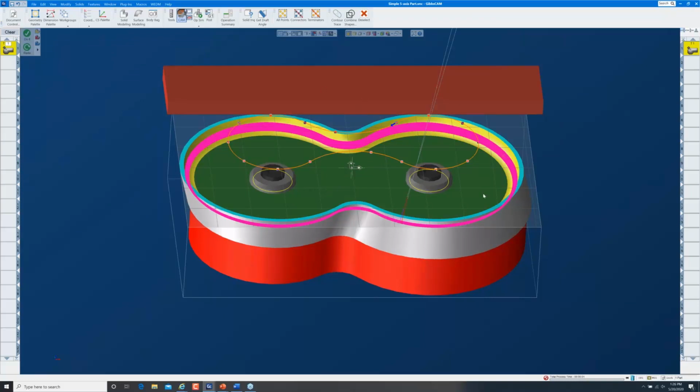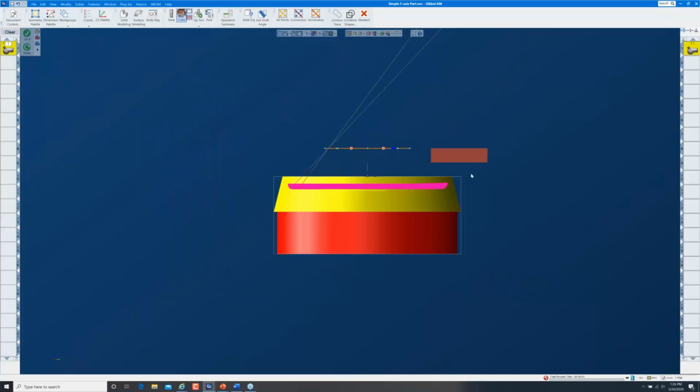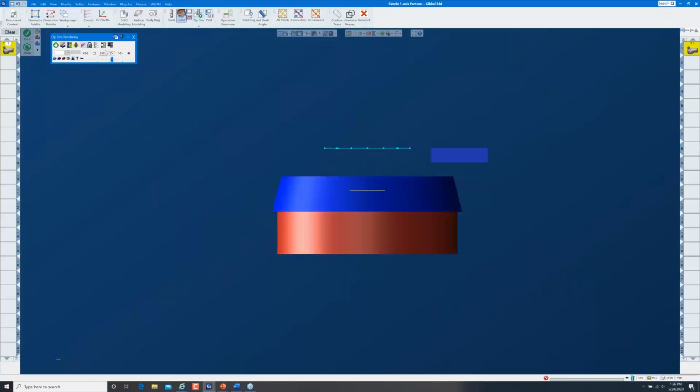Let the toolpath recalculate. And I'm going to go down to an end view here and go back to my simulation. And I'm going to put my point of view lock on fixed part and run this. And what I want to see is if that tool is tilting. I'm going to slow it down a little bit. And you can already see that it's tilting below the curve as it comes around here. It's tilting more than it was on the other side to keep the tool away from the surfaces that we're checking against.